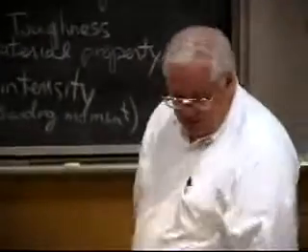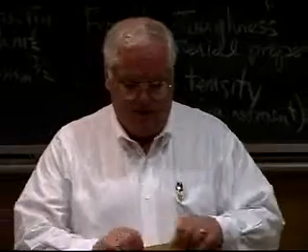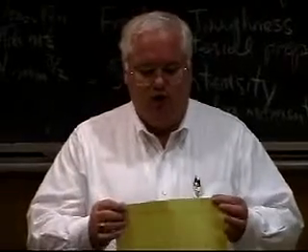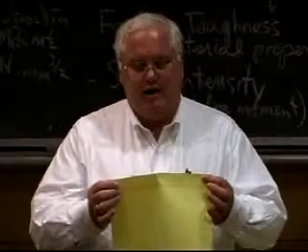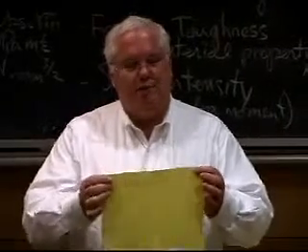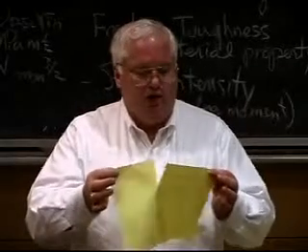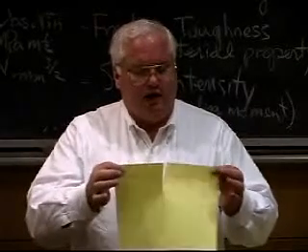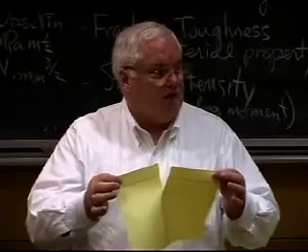However, we can go back to that simple little edge crack, and we know that by putting a defect in the surface of something, I can weaken it substantially. But what am I doing? You see the bending moment I'm putting on this? I'm pulling in tension, but I'm putting a bending moment on it. And in fact, the bending moment increases with the length of the crack, right?